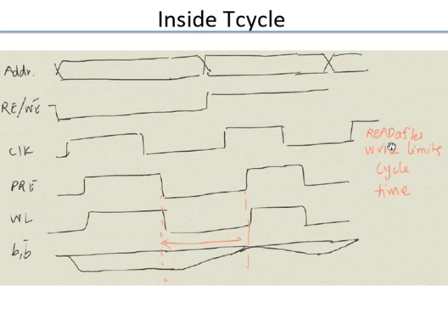That means you do a write in a particular row, but then you read maybe from a different row. But both these accesses use the same bit lines, right? The bit lines are shared. There's a single bit line in which you either pump data into the cell or you read data from the cell. So it's a shared resource. So how quickly can you turn around the bit line? Really, that's basically what limits it, because the bit lines usually will be large, a lot of capacitance.